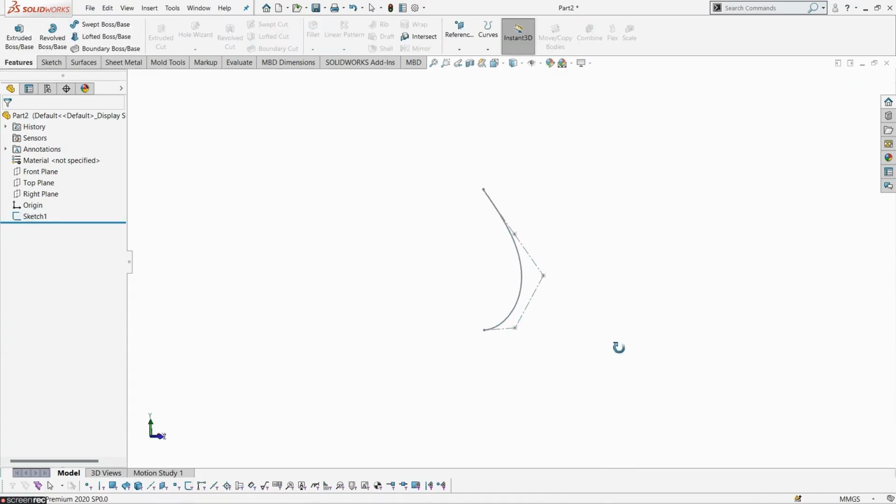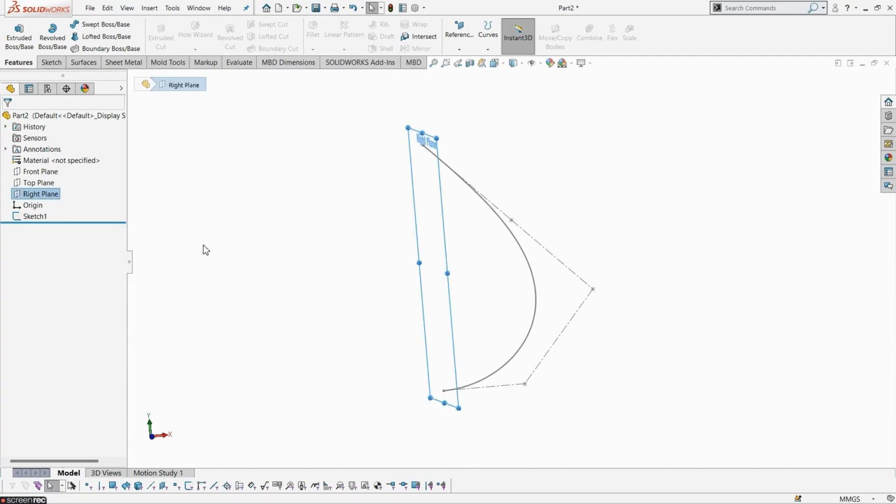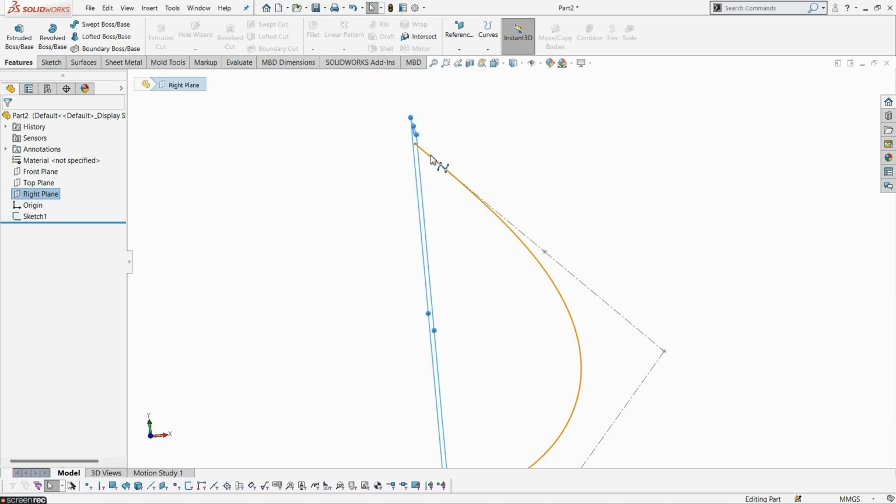And now we need to draw a profile at the particular origin point, because this is a path curve. Before creating any profile at the point, first we need to understand the exact location where the profile should be placed. The top endpoint is slightly tilted, while the bottom endpoint is fixed at the origin point itself.